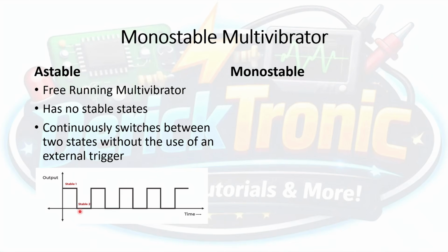If you remember from the previous video, the LED connected to the output was switching on and off, on and off, on and off by itself, without any external trigger being pressed on the circuit itself. It's just turning on and off by itself. That's why the astable multivibrator is known as a free-running multivibrator, because there are no external triggers, and it also has no stable states. Now, for the monostable multivibrator circuit, these are its key characteristics.